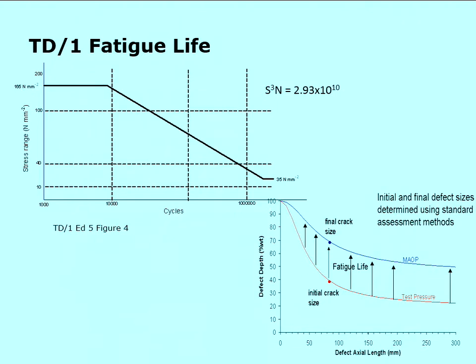Right, there's a couple of diagrams in, and these are in the notes as well, which are basically just showing how current standards are structured. Most standards start with a lot of emphasis on the route, safety, environmental and constructability, and require you to follow quality assurance, the various safety and environmental management systems, and also the pipeline integrity management system.